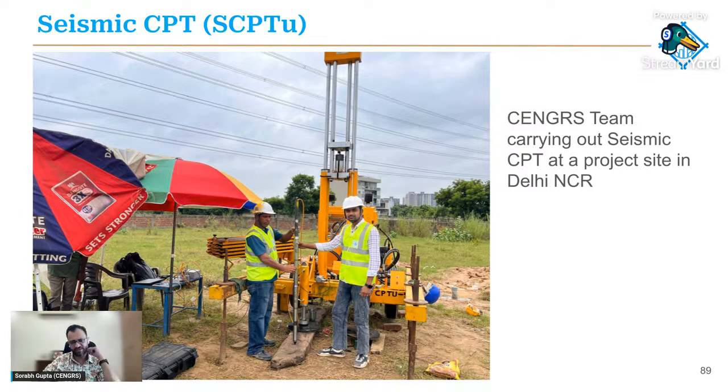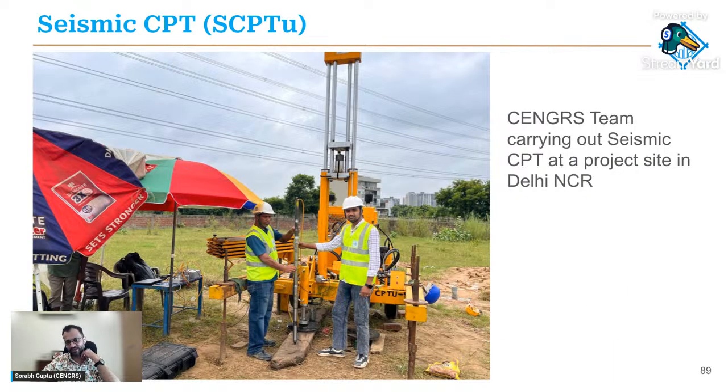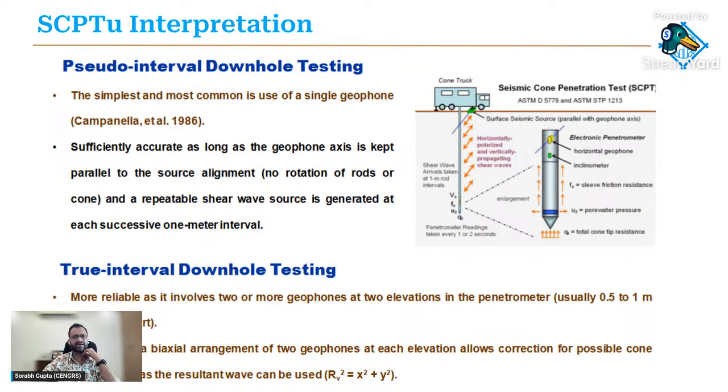So we did this very recently, the seismic cone. This is, in fact, as early as last week. We were doing a seismic CPT at a site in NCR. The interesting thing is, because there is no borehole preparation required, there is no grouting and grout setting required, the seismic CPT gives us very, very clean data as compared to borehole methods. More on this in times to come, but this is our first observation.